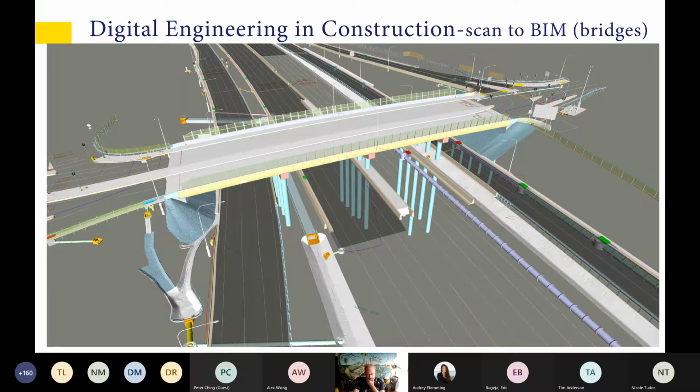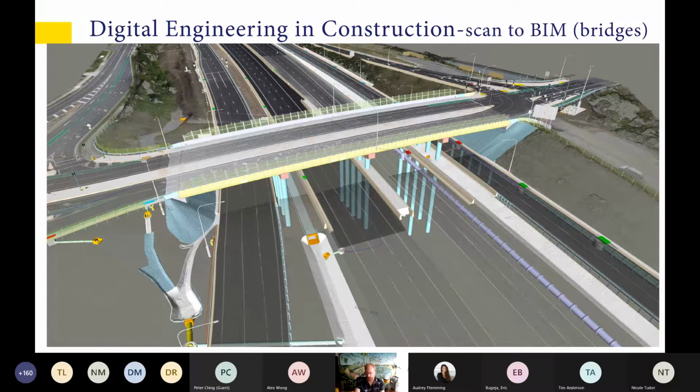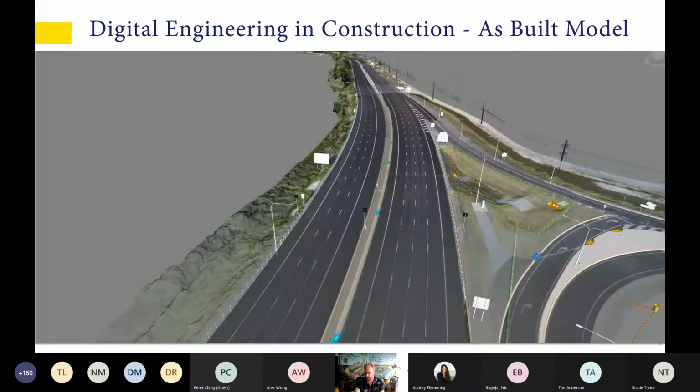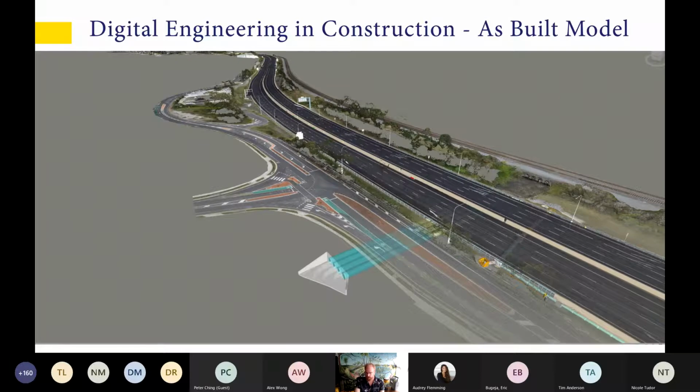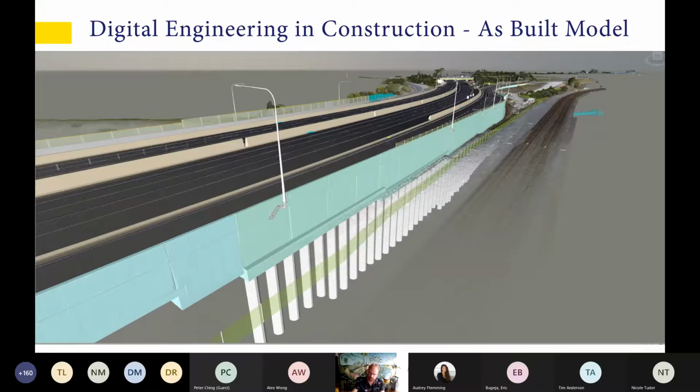What we did do though was we used these 3D face sets, which allowed us to embed sampled point cloud data into the surfaces. So there's a direct relationship between the objects that are built and the measurement of them. So they are in the place they're supposed to be. So there's just a couple of views of the one that we were looking at. You can see that stippled area, that's because it's actually taken using the resampled point cloud as the vertices in the mesh on the face.